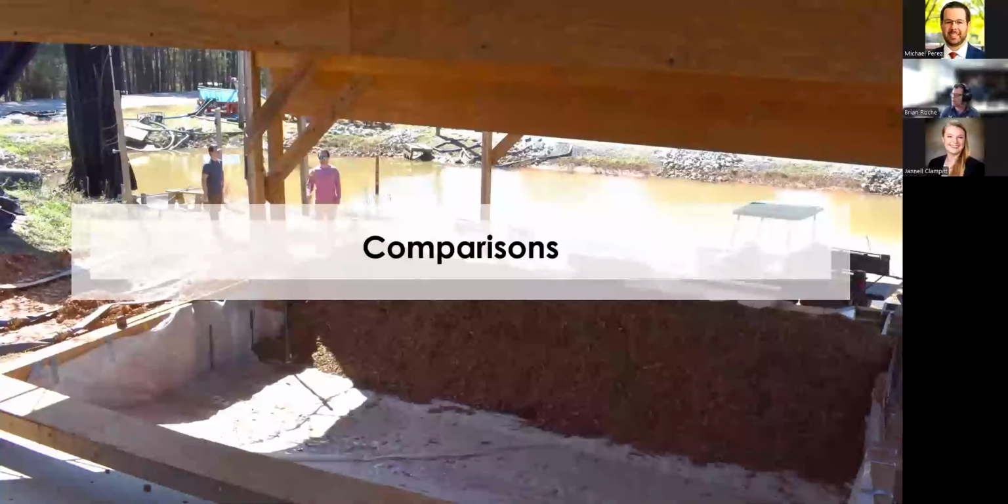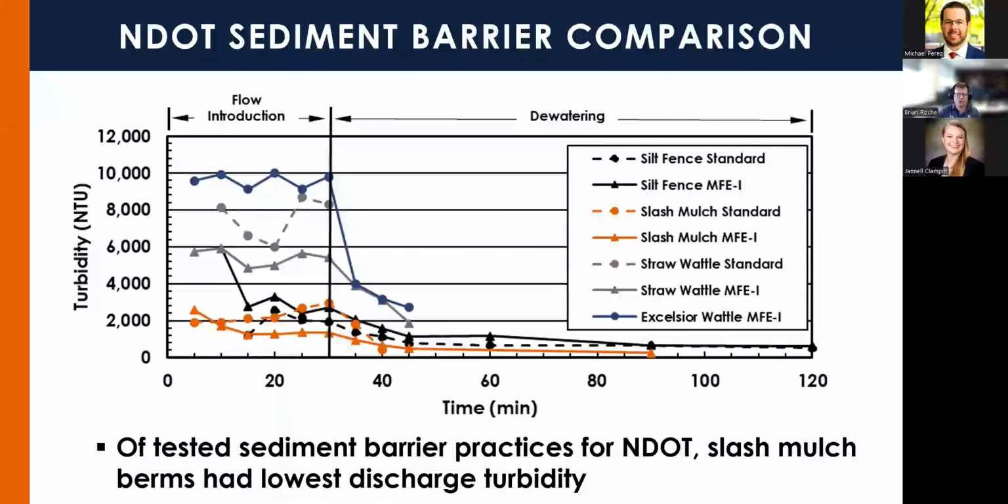Now I just want to make some comparisons between the performance of our slash mulch berms and other sediment barrier installations we tested for the Nebraska DOT. Here's a chart showing our turbidity over time for silt fence, standard modified installations, slash mulch berms, and our straw and Excelsior wattles. Of these practices, our slash mulch berms had the lowest discharge turbidity. Even the standard, which is that orange circle with the dashes, showed lower discharge turbidity than most of the other installations we tested, with our most feasible and effective slash mulch berm installation performing the best in discharge water quality.